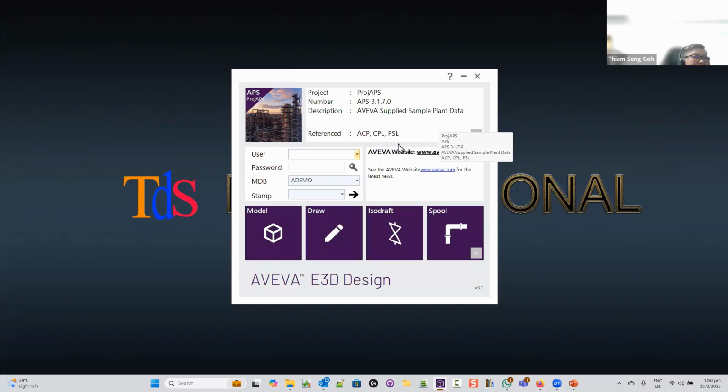Okay, there's a question there. I will go back to answer your questions when it is relevant, okay? So the first thing is that a project can reference other projects. Can you see the word reference there? So in E3D, it's very flexible. If your company has got a set of catalog and a set of specification, you put them as a reference project. And the moment anybody runs a project that references this project, he can make use of your catalog.